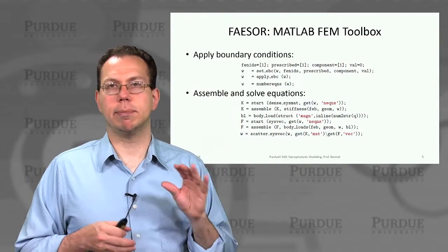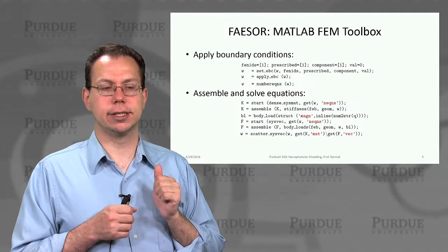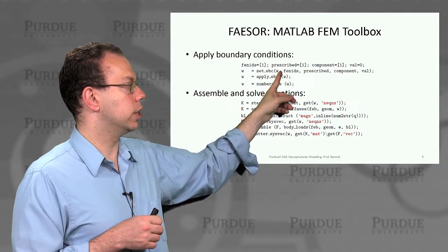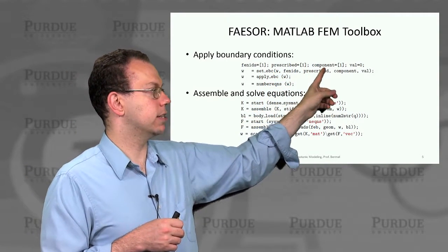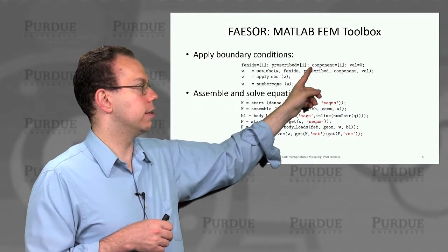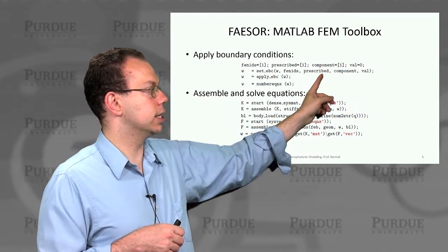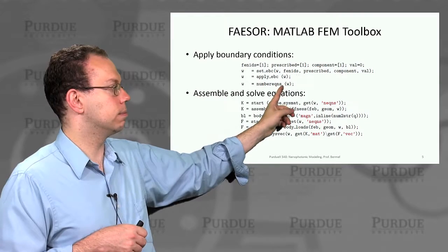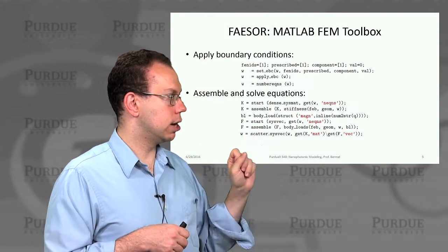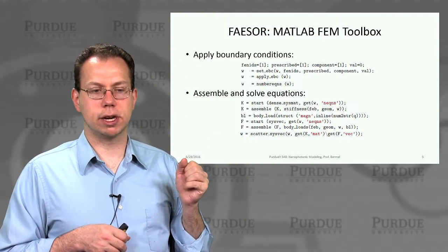And so once you have that basic setup, the core of the problem, then you have to apply the boundary conditions correctly. This is showing how you can create these. Here, we're just specifying a prescribed value of 1 at some position and then a value of 0 at the other side. So this is setting the boundary conditions explicitly, the set EBC and apply EBC terms. And then W is now generating the equations that are associated with those boundary conditions.